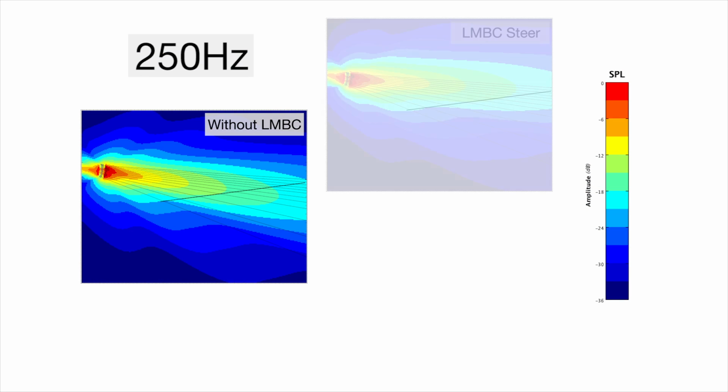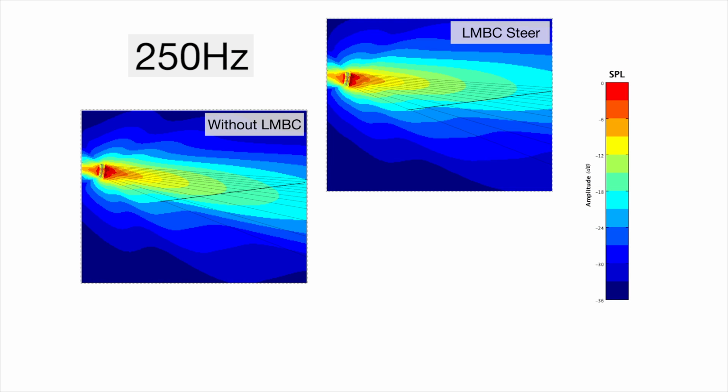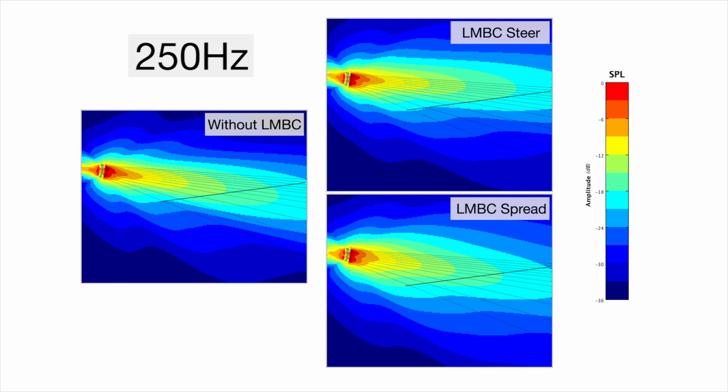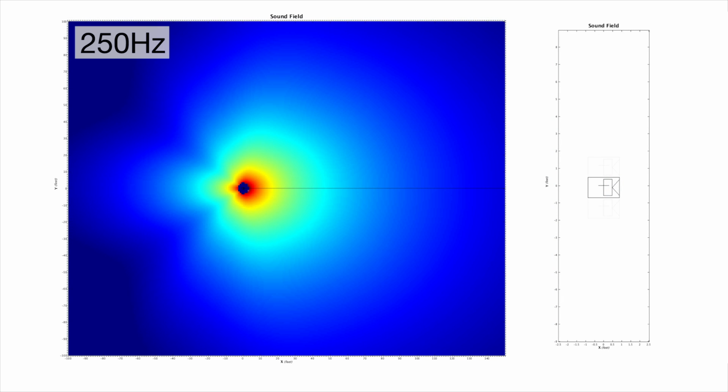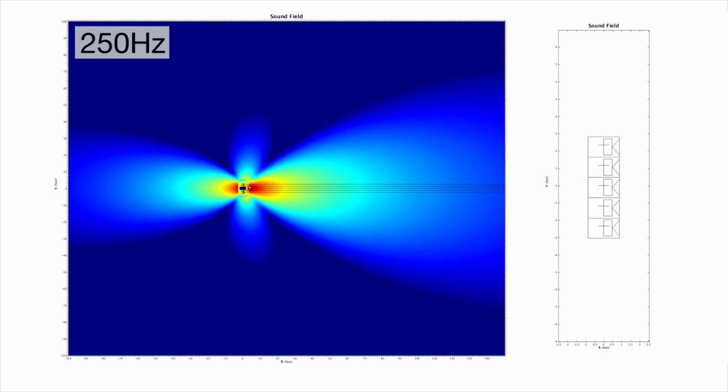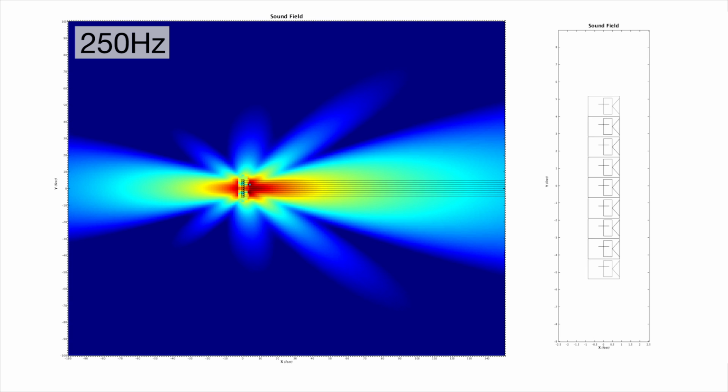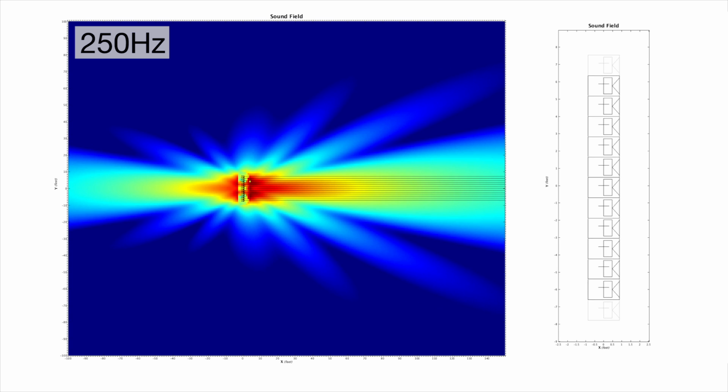Active phase steering with specialized signal processing provides us with the capability of aiming and controlling the beam in new ways. This method is far less intuitive than simple amplitude steering, since we are bending the sound in directions different from where the speakers are aimed. In the low-mid range, there are virtually no level offsets between the individual arrivals. The phase offsets drive the coverage to narrow toward the center, phase steering. And the low-frequency coverage is narrowed to less than a single element.